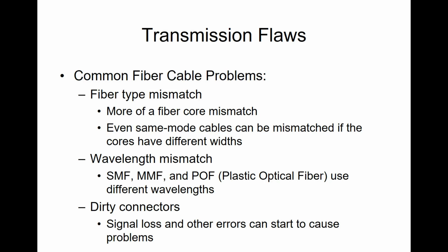So there's a couple of other things that can happen. On fiber, there's a couple of different core sizes. And so we have to match the transceiver with the core size. So the one that's going around is matched for a 50 micron core. That transceiver, if I plug in a 62.5 micron fiber, it'll work, but it's mismatched. It doesn't run very well. So picture Usain Bolt, but wearing shoes that are too small. Is he going to be able to run as fast? No. So you need the core of that fiber and your transceivers to match.